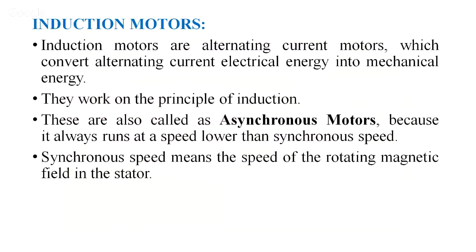Let us learn about induction motors. Induction motors are alternating current motors which convert alternating current electrical energy into mechanical energy. They work on the principle of induction. They are also called asynchronous motors because they always run at a speed lower than synchronous speed. Synchronous speed means the speed of the rotating magnetic field in the stator.